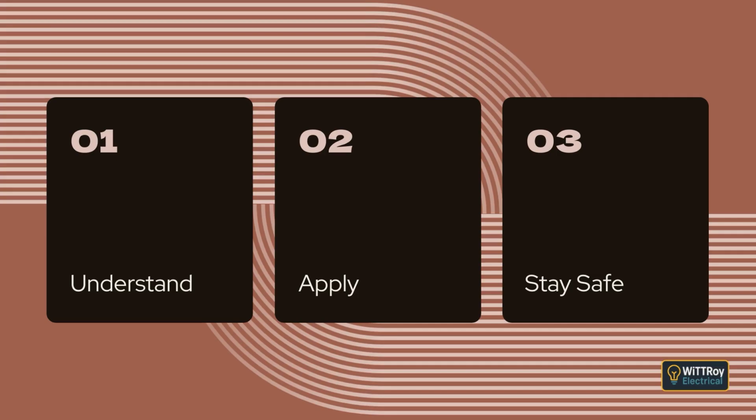Clause 3.7.2.1.2 Aluminium conductors. Aluminium conductors need special care. Joints and terminations must use parts specifically designed for aluminium and must follow the manufacturer's instructions. When working with aluminium, the oxide layer must be removed, the softness of aluminium must be considered, and differences in expansion rates between aluminium and other metals must be taken into account. The conductor must also be protected from contact with dissimilar metals that can create galvanic corrosion.